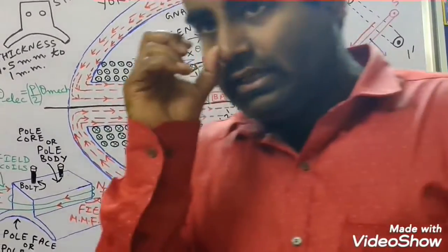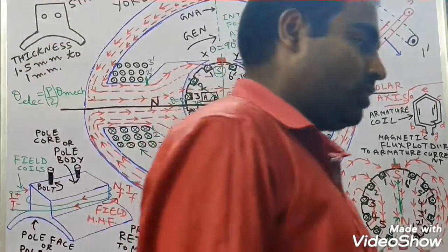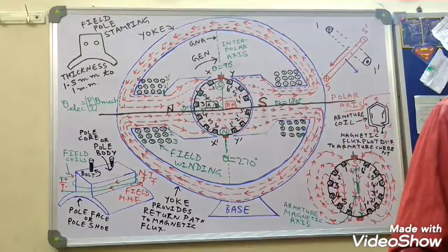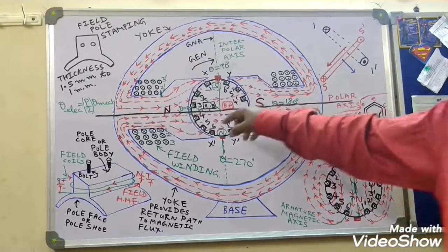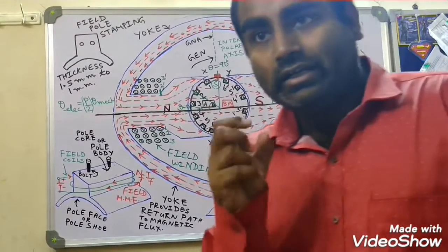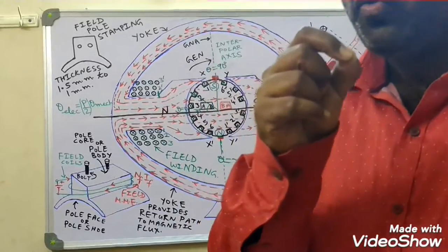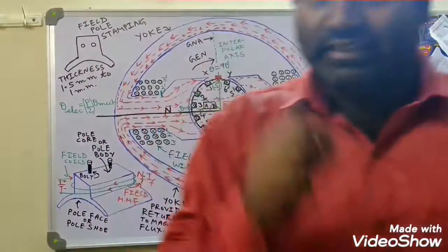So in order to find the armature MMF variation, we need to take the developed view. But for taking the developed view, we have to imagine that we are cutting the armature core at some point. So where will we be cutting? Listen carefully: we will cut the armature core at that point where no magnetic lines of flux are leaving or entering the armature core.